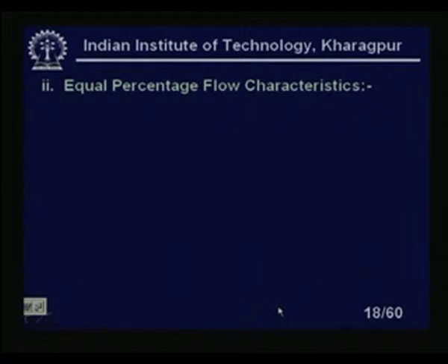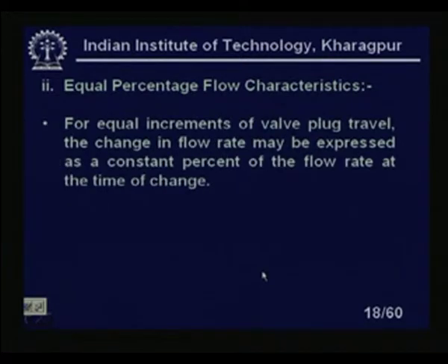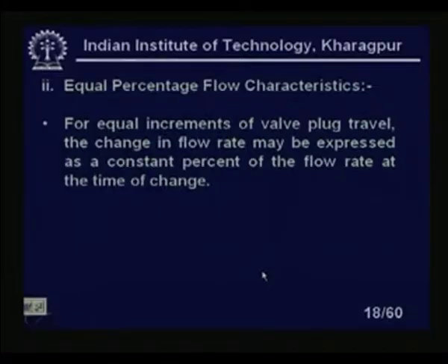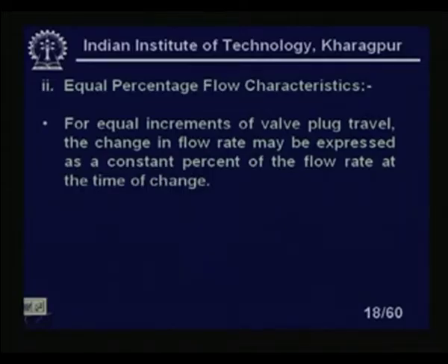Equal percentage flow characteristics. We already discussed the linear characteristics. Let us look at the equal percentage characteristics. For equal increments of the valve plug travel, the change in flow rate may be expressed as a constant percentage of the flow rate at the time of change. Gain is not the same, but for equal increments of valve plug travel, the change in the flow rate may be expressed as a constant percent of the flow rate at the time of change.